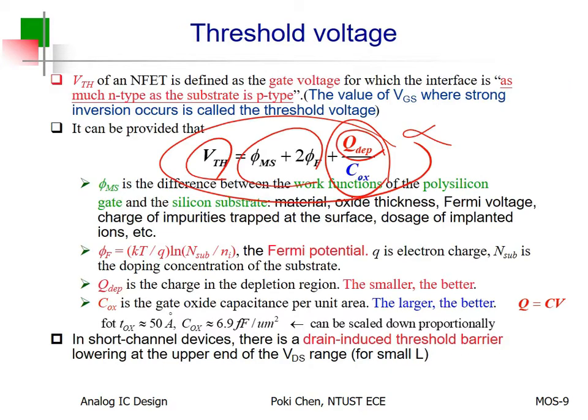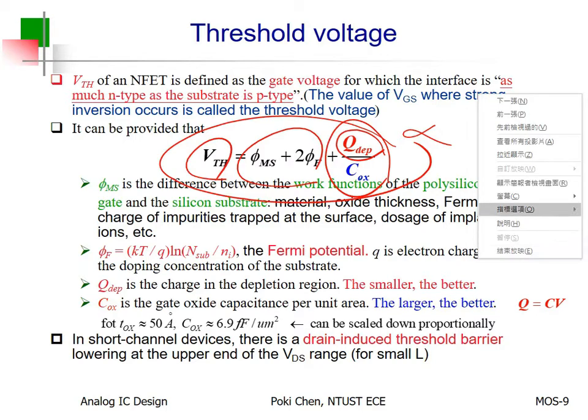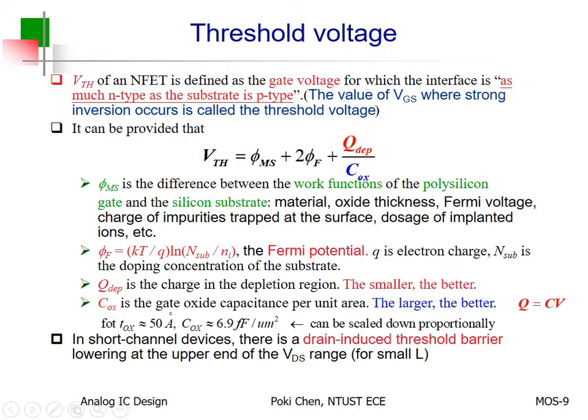So, I try my very best to explain why VTH has this term. It is very important. For all of you, I think you would like your MOSFET to run faster. Okay? But how? You need to reduce VTH. How to reduce VTH? Two ways. First of all, reduce the number of holes in the depletion region. Anyway, reduce the doping concentration. The lighter doping, the better for conduction.